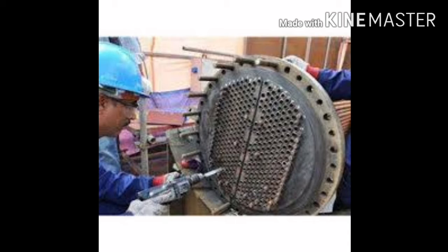It will clog the tubes. This fouling can adhere to the walls of the equipment's tubes and pipes, as well as inside various valves and flanges, thus causing the exchangers to reduce heat transfer. It will reduce the heat transfer.